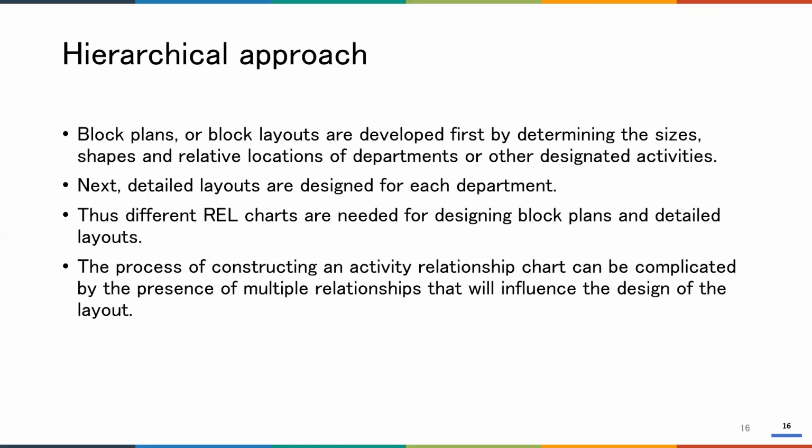And in the hierarchical approach, we make several alternatives. We can calculate it using the way that I already explained to you before, either by the load distance metric, or by the calculation of the layout score based on adjacency.